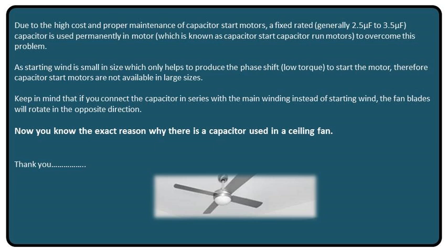Keep in mind that if you connect the capacitor in series with the main winding instead of the starting winding, the fan blades will rotate in the opposite direction. Now you know the exact reason why a capacitor is used in a ceiling fan. Thank you.